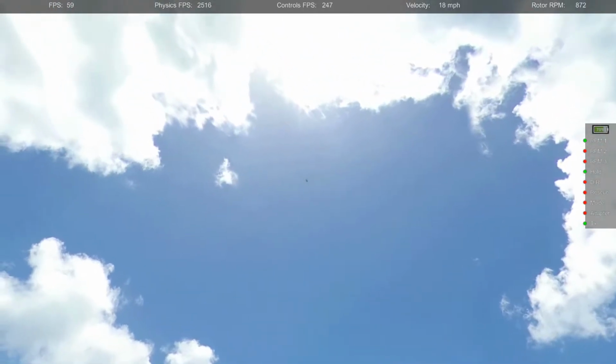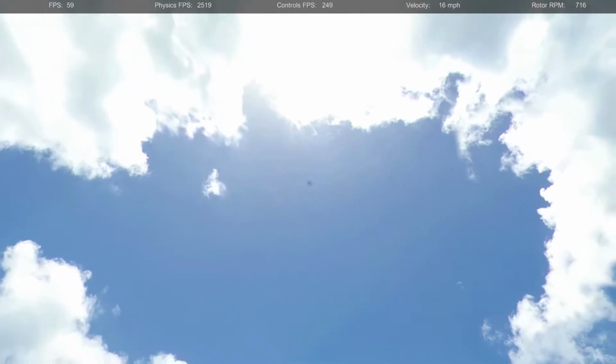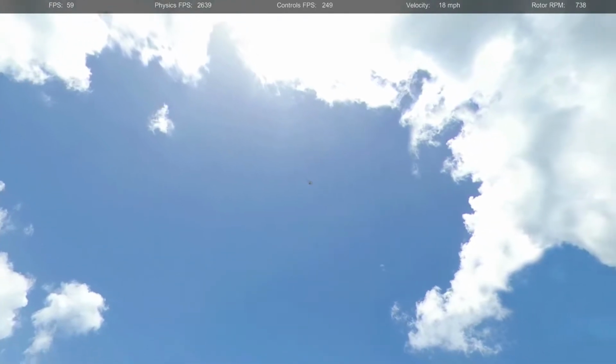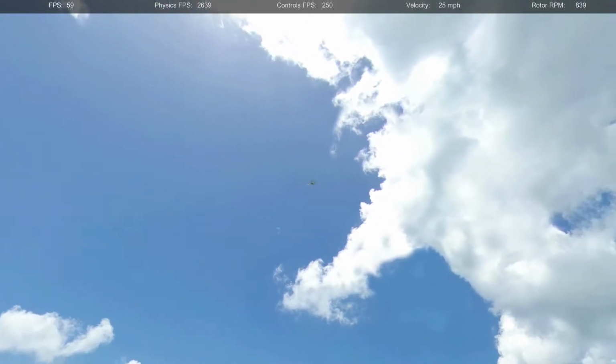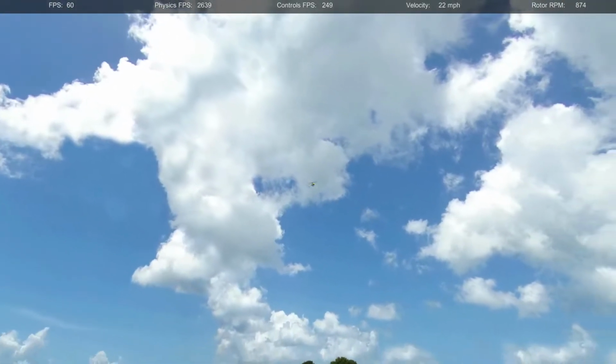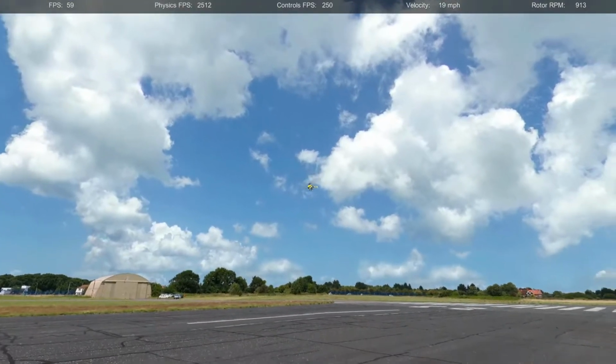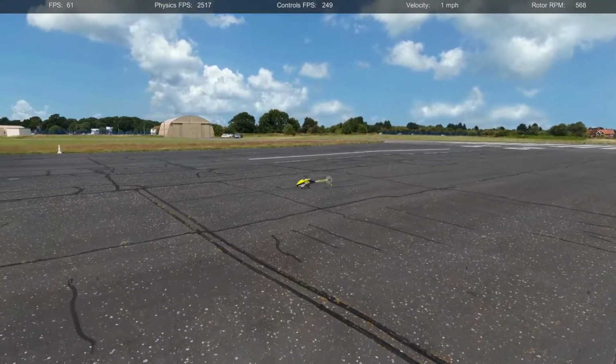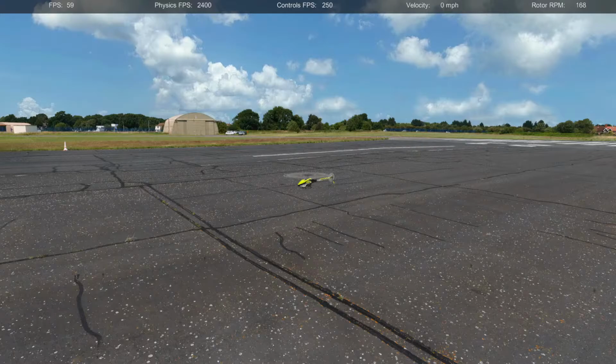And so there's a sag in the middle of the wing where you get the two wings coming together. And this sag is in the lift. And so you don't get as much lift. And so the vehicle ends up feeling like it's nose heavy. And so it turns out there's a way to overcome that. And I've been using this trick by changing the incidence of the wing through the center section.